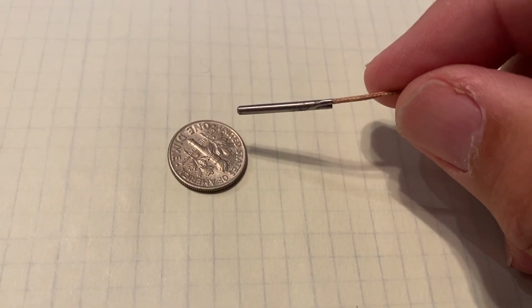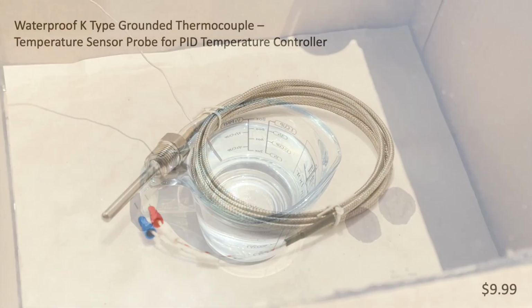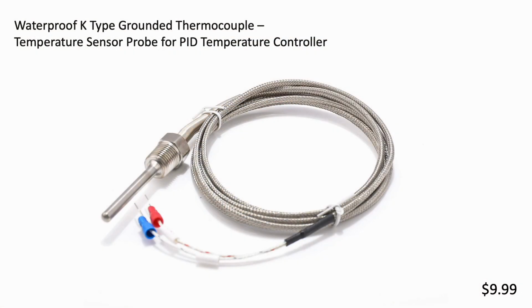We also learned that it helps to have a more robust waterproof sensor to measure temperature in liquid environments. In response to these challenges, we eventually upgraded our thermocouple to this model. This has a more robust sensor housing and better terminals for tying things together, in addition to a 2-meter stainless steel sheath for being able to stand away from the solar oven while taking measurements.